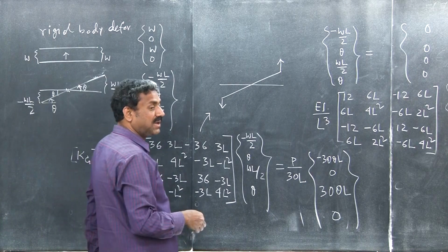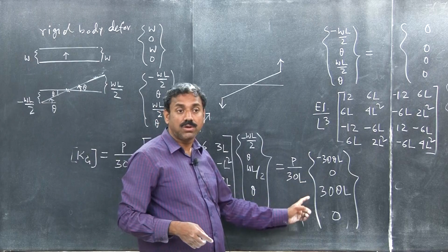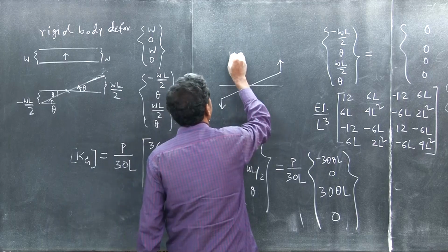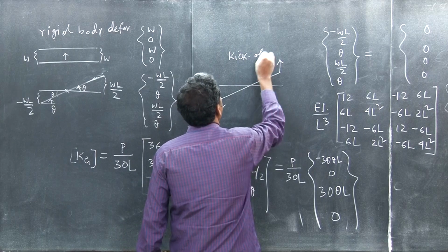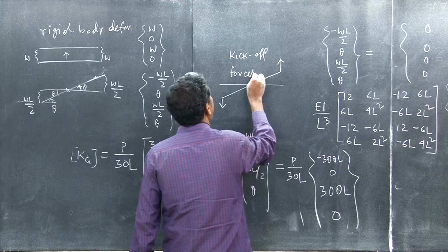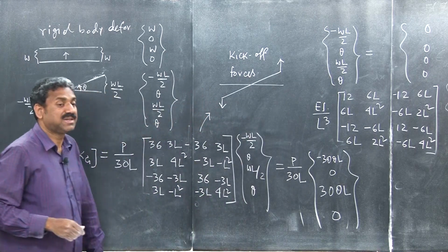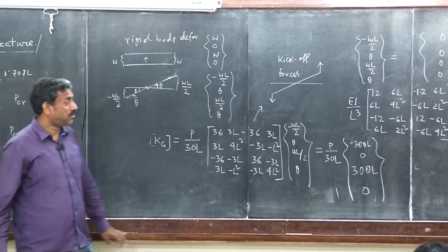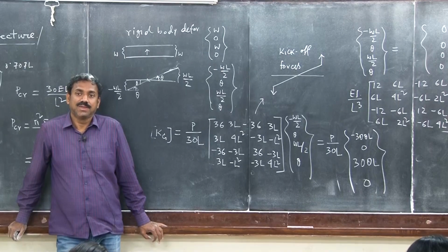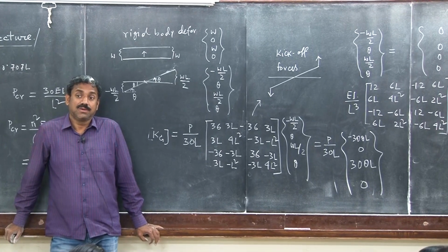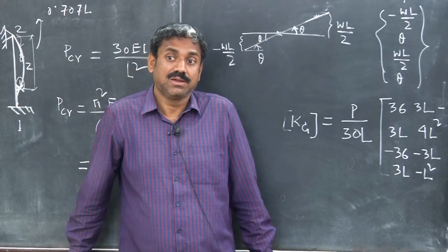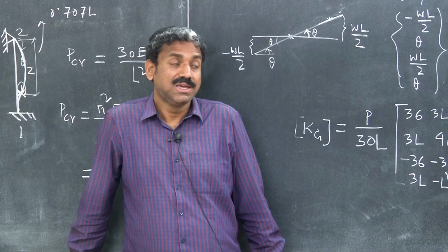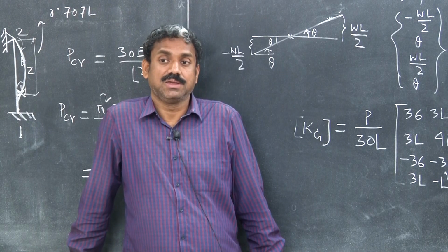These forces, so that means rigid body modes are not shown by the geometric stiffness matrix. These forces are kick-off forces. That means, why is it happening? Why is the geometric stiffness not allowing the rigid body modes? The reason is that we are only considering the del W del X square, we have not considered the whole geometric nonlinear term. So there is an inconsistency in geometric compatibility.